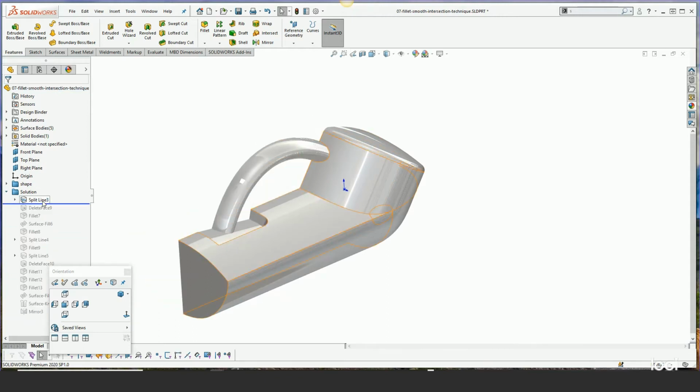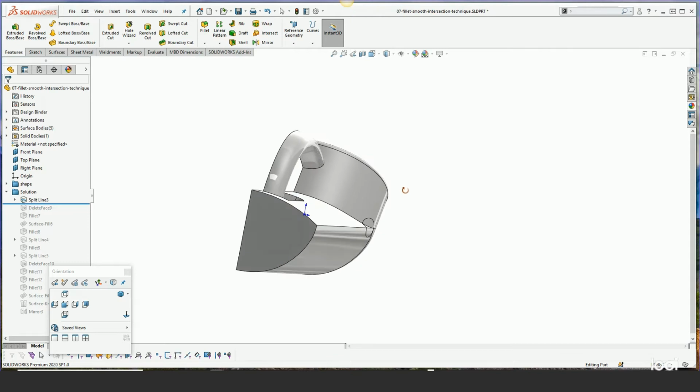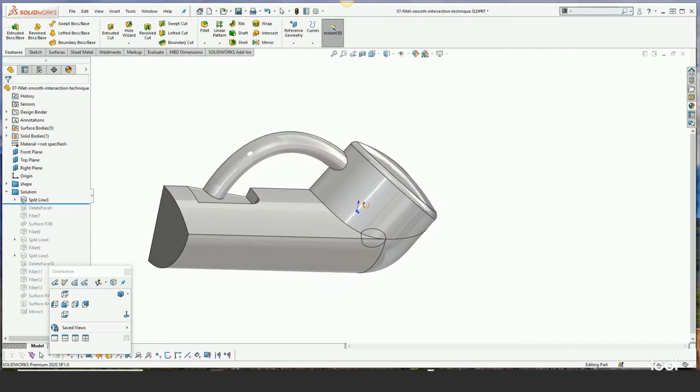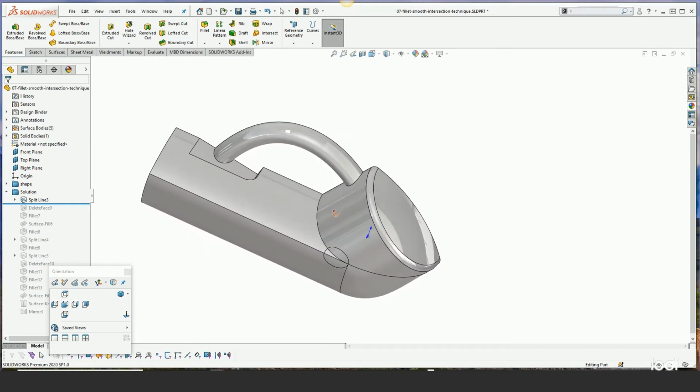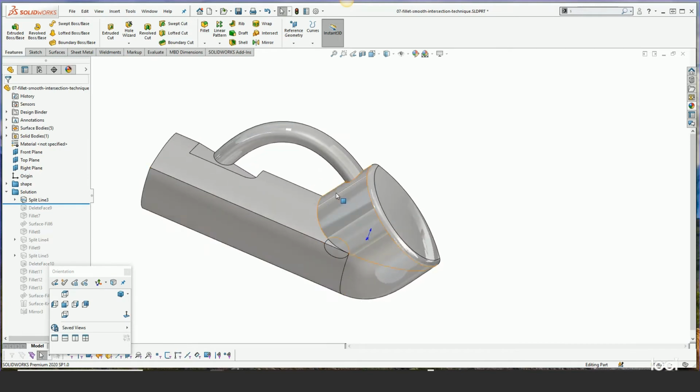So the first thing that I need to do is I need to isolate the problem from the actual fillet feature. And one way of doing that is by using what is called the Atomic Bomb Fillet, which is known in the SolidWorks community as an old-time favorite. I can't remember who actually had created that term and first showed it, but whoever they are, they're brilliant.